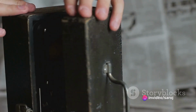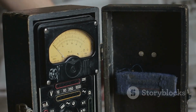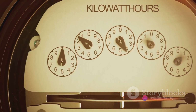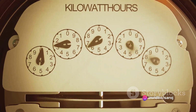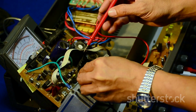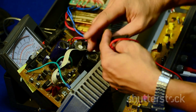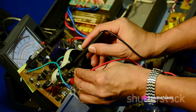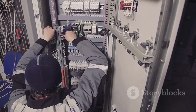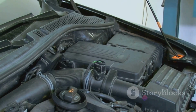Now, how do we measure this force that's so vital to our daily lives? We use a device called a voltmeter. A voltmeter is a tool that measures the voltage or potential difference between 2 points in an electrical circuit. It's like a ruler for electricity, but instead of measuring length or distance, it measures force or potential difference. The voltmeter works by connecting in parallel across the component or points where you want to measure the potential difference. This means it's hooked up alongside the part of the circuit you're interested in, not in series with it. This is important because it allows the voltmeter to measure the voltage without significantly altering the current in the circuit.